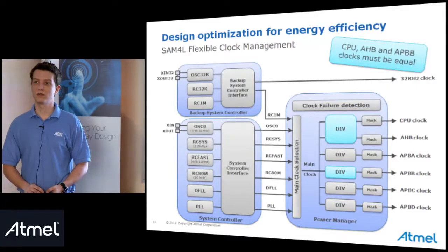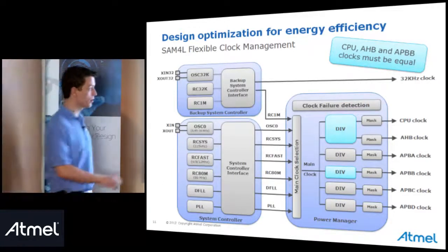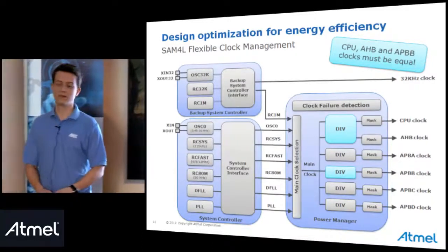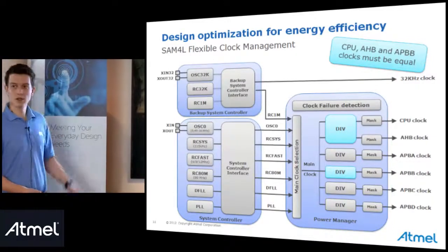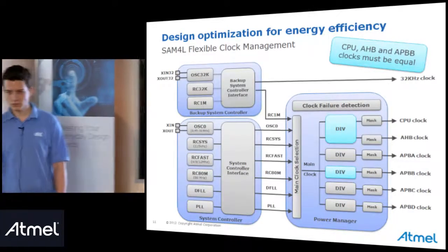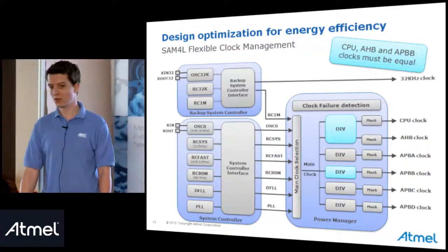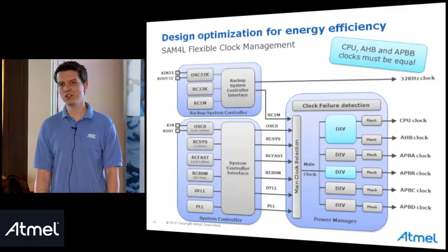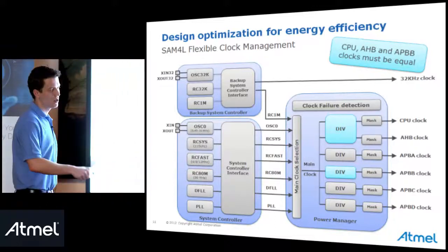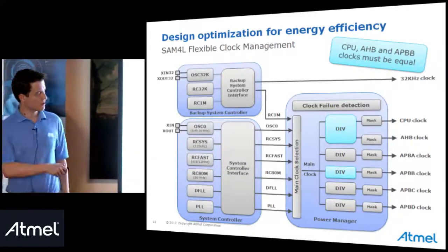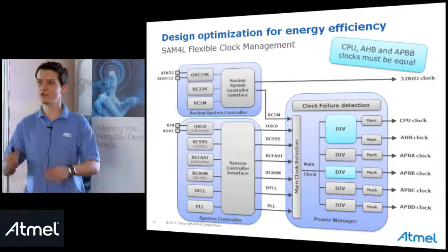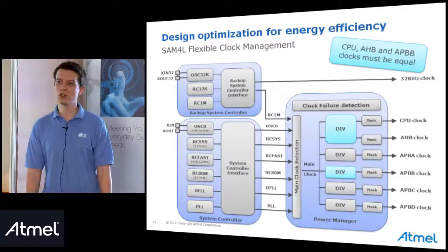But is the CPU clock running? Yes, sure. You mean the system clock? Everything is running. If everything's running, don't you have peak current at startup? Yes, you're right. Let me check, because I know that at least the peripheral bridge clocks are running. System clock, yes. CPU clock, yes. So yes, you should have a peak. Then after, you need to fine tune what you want to do.